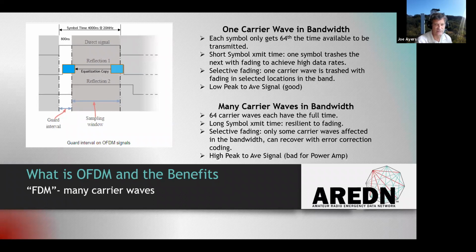What that means is that if the signal has a high peak to average power ratio, the power amp can get saturated more easily or go out of linearity. Therefore, we start getting a loss of signal quality, out of band emissions, and data loss.